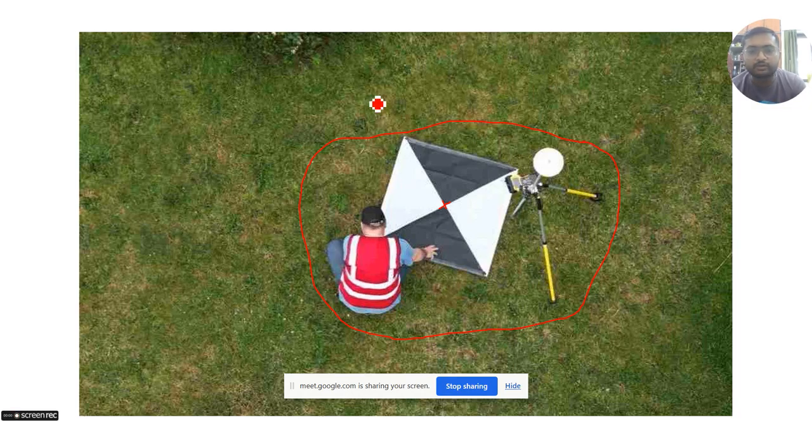So I will take the corner of a building as a GCP, and then go with my GPS and collect the point of that particular corner, or that particular part of the temple or bridge. Then even after 5 years, if I want to use the same thing as a GCP, it will not hamper the geometric accuracy or precision of your image.